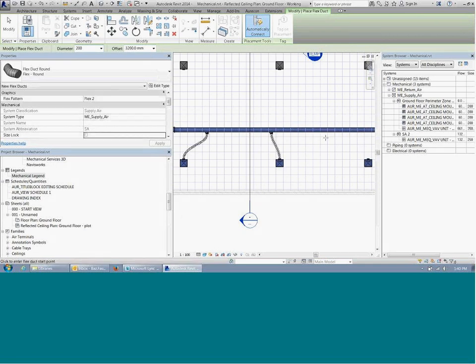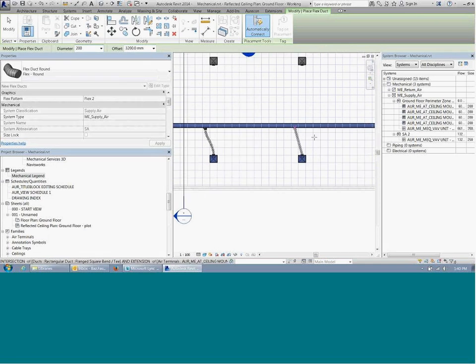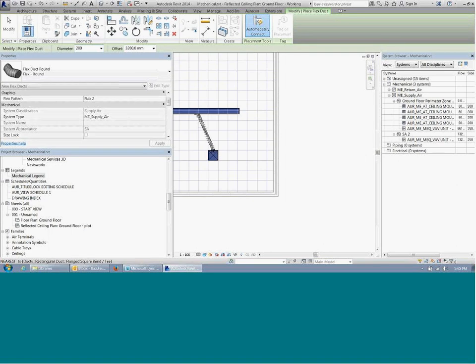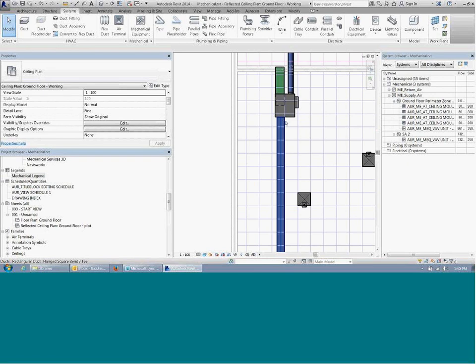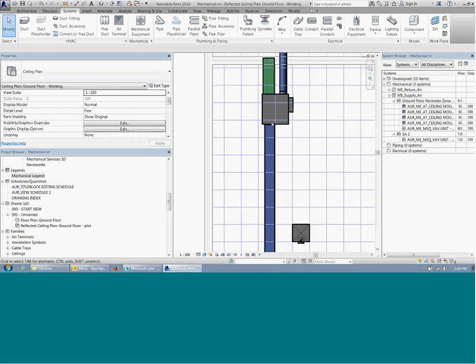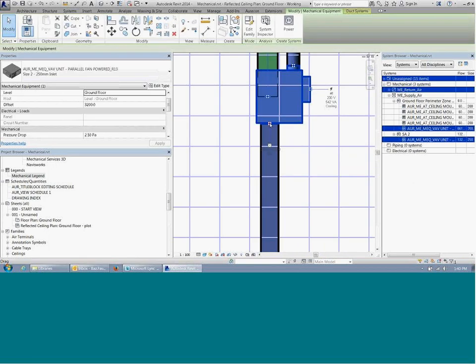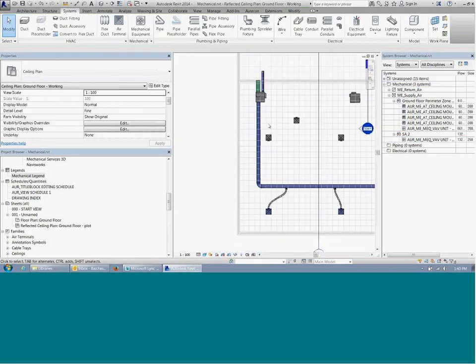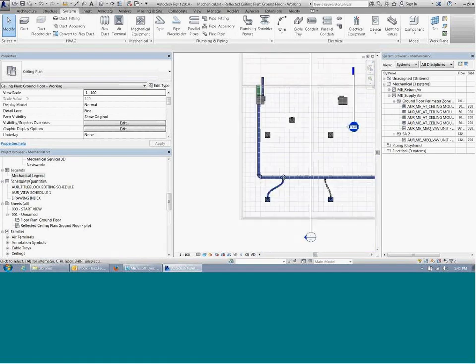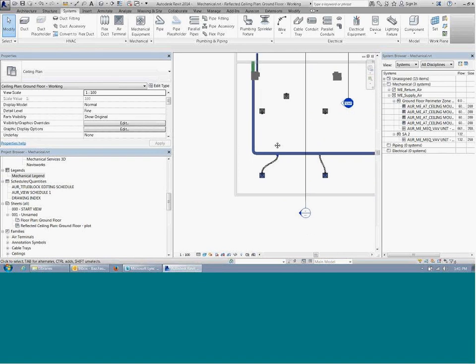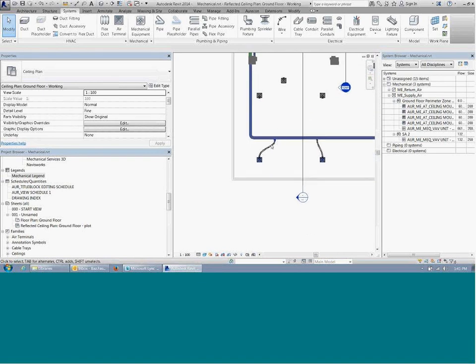So if we do that for all these grills. I can't remember seeing you get the height of the duct. Is that because you've got the VAV? Yeah, it just inherits the setting from that MEP ductwork connector here. When you right click the air terminal, even though it knows where it is in space, it doesn't know where it's going, because that main duct could be anywhere. I get it. That's right.